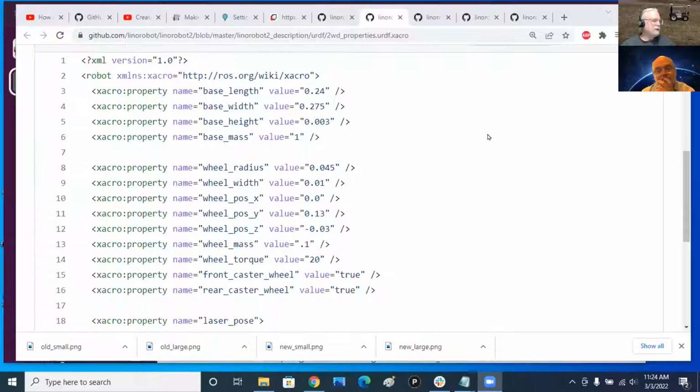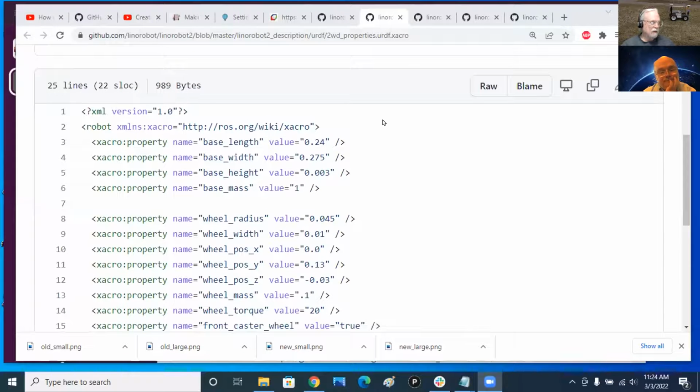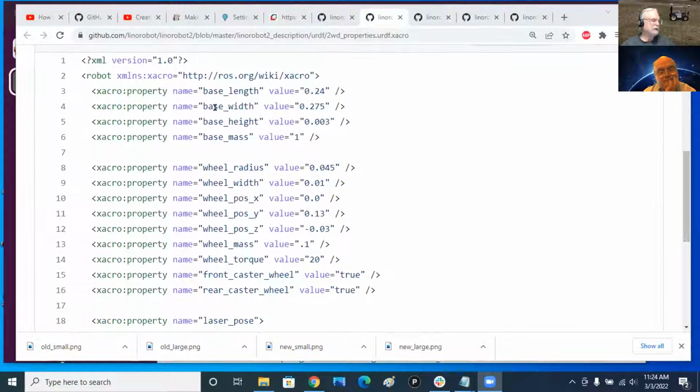And go to this page. So if I say share screen, this screen. So we had this screen up, and it's just one of the mini Xacro files that are all tied together here. And in here, it's defining properties. So properties is an extension you can put on top of everything else that's there. It's essentially like in Python or C, where you're doing a define or just creating a variable. So here, it's just assigning a name of base_length to a value of 0.24.